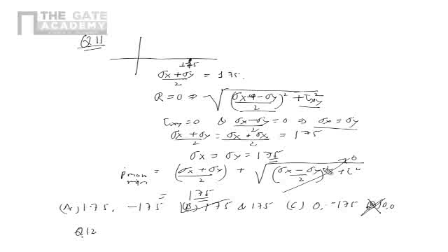Now let's see question 12. What does question 12 say? Determine the directions of maximum and minimum principal stresses at point P from the Mohr circle. Now see, principal stresses are equal, which means every direction is a principal stress direction. When the two principal stresses are equal, it is like a fluid pressure P. Every location, every direction in the fluid has the same pressure. Similarly, when principal stresses are equal, it directly means that from all directions the stresses are equal.